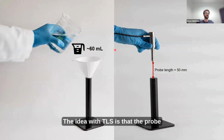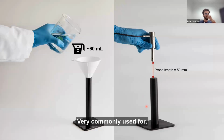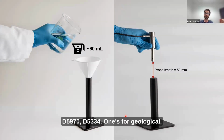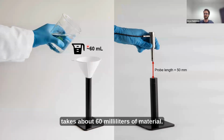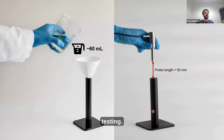The idea with TLS is that the probe is immersed or inserted down into the body of material that we're testing. There are two ASTMs for the TLS. It's ASTM D5970 and D5334. One's for geological, one's for polymer-based testing. But the idea is, there's a standard cell that we provide, which takes about 60 milliliters of material. You would insert your probe down in and then go about your testing.